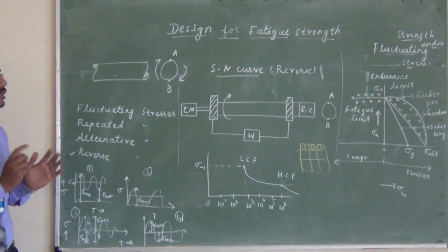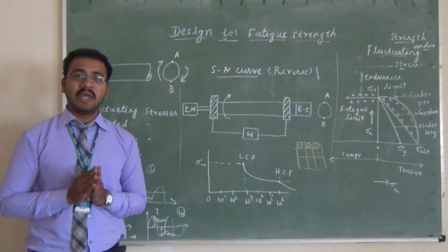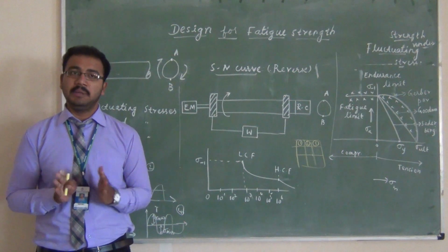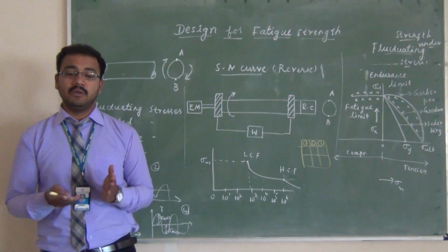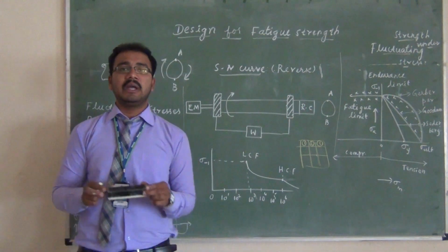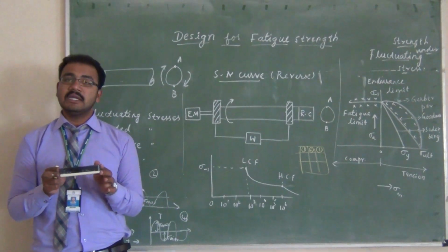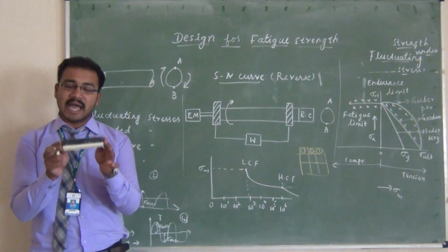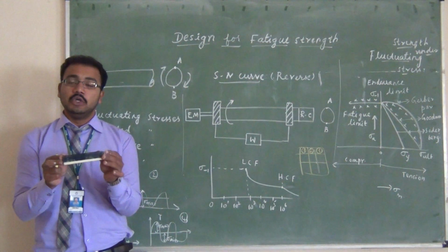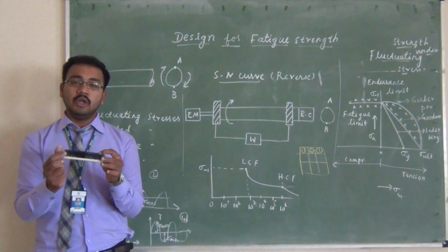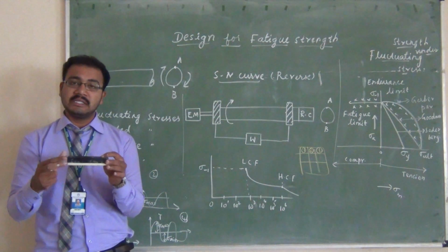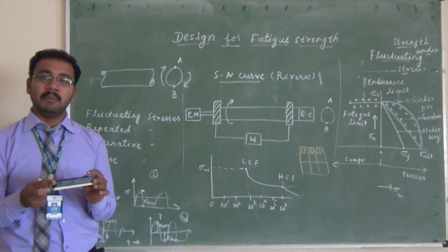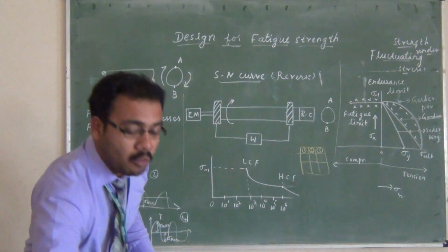So now we come to the concept of fatigue. What is fatigue? How can we define fatigue? Fatigue is nothing but the tiredness which is achieved by any body. How can we explain what is meant by tiredness? Say for example, let me consider a small metal body which has an ultimate strength of some 100 Newton per mm square. When any external load is acting on this component, usually the failure will happen when the load surpasses this yield strength. But in case of fatigue, before it achieves its 100 Newton per mm square, the material will fail because of the tiredness.